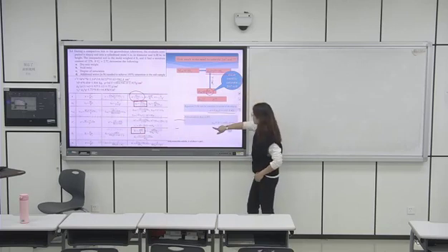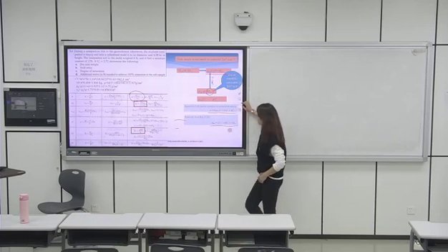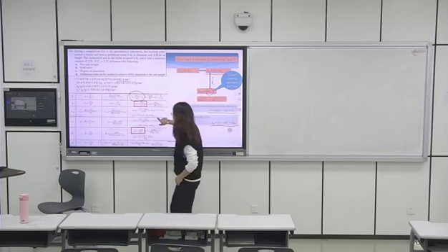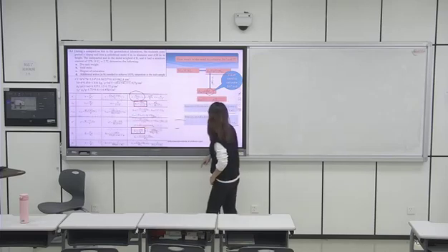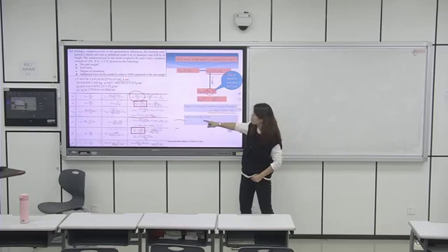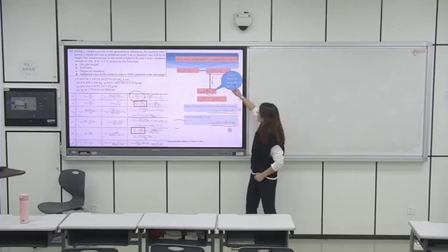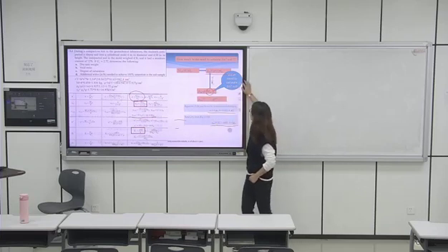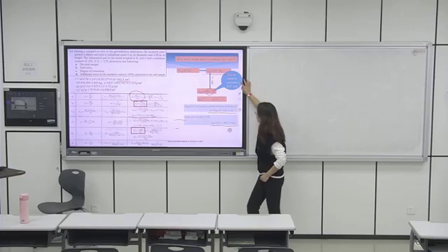And again, for saturated density, it equals this. You see, it is actually very similar to this. So with these two equations, we can get rho sat and rho. And the difference between these two is the water needed to saturate 1 cubic meter of soil.